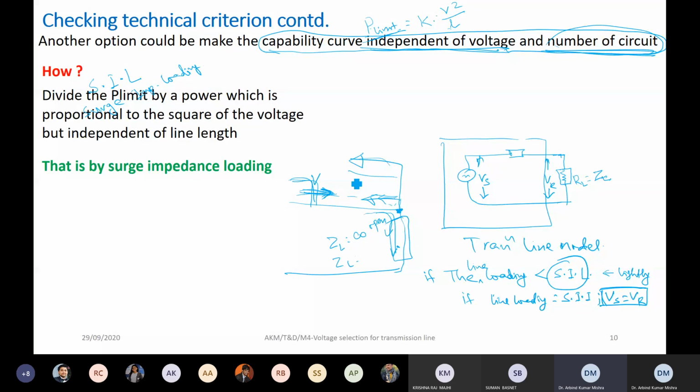And I have told you that the variation in the GMD upon GMR is from 400 to 1200, and because of that, inductance per unit length of a line is almost virtually constant. Similar thing you can expect for the capacitance as well, isn't it? Because the capacitance expression is also 2 pi epsilon divided by ln GMD upon GMR.